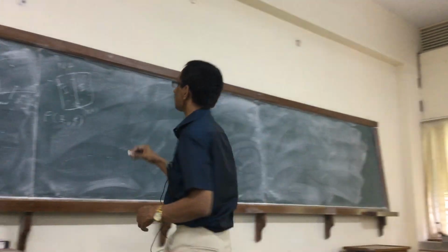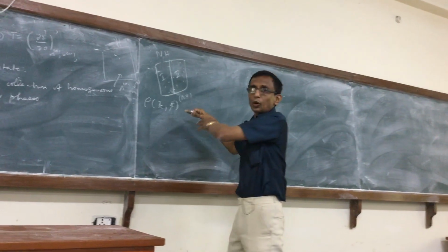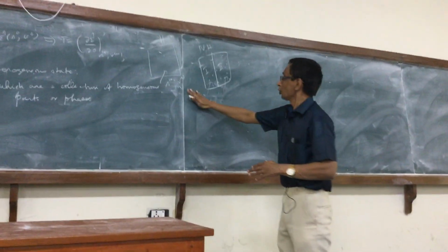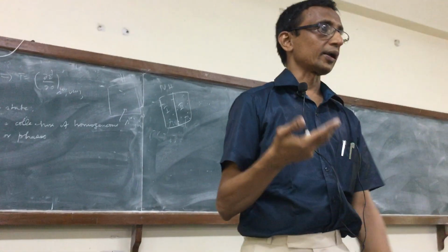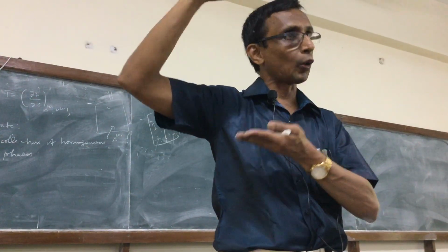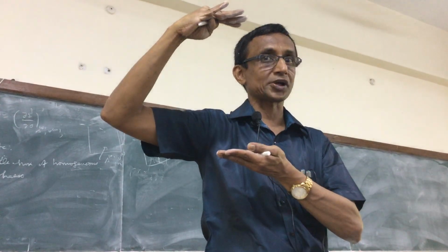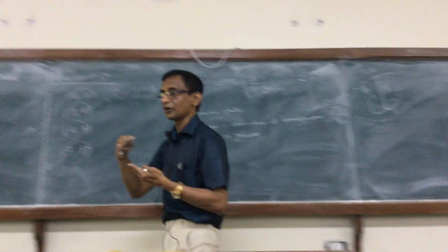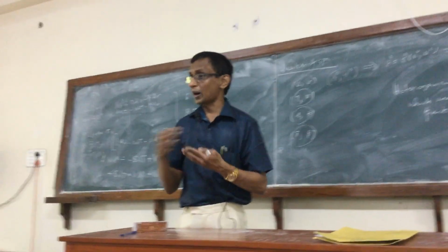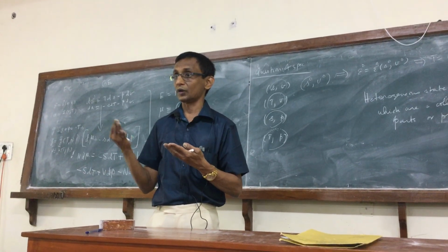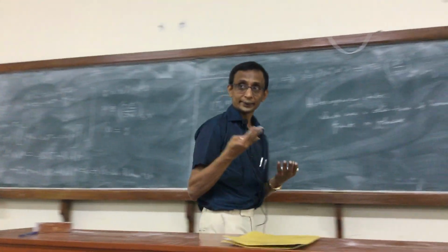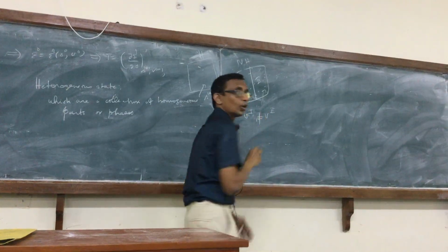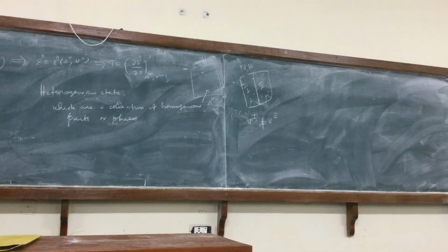Okay? So what it means is that if you look at the system overall, there is heterogeneity. The properties of this would be different from that of this. For instance, water boiling at 1 atmosphere and 100 degrees centigrade, that is, has liquid and vapor both existing at the same temperature and pressure. Temperature and pressure are the same for both the phases, but we know very well that the specific volume of the vapor would be much different from that of the liquid typically. Could even be orders of magnitude greater, right? So that is one quantity which we know is not equal between the 2 phases.